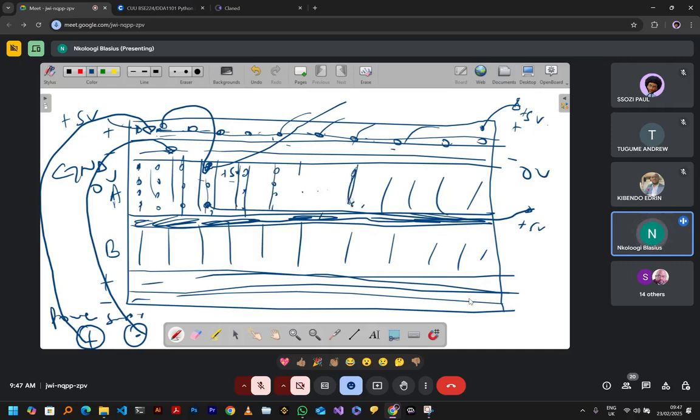And what happens on rail A is what also happens on rail B. You can also supply ground here and tap it from this side. So these are always vertical arrangements, yet the ones on top and bottom are horizontal arrangements on the breadboard.